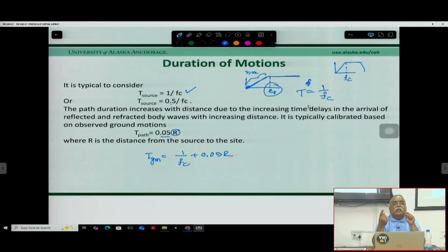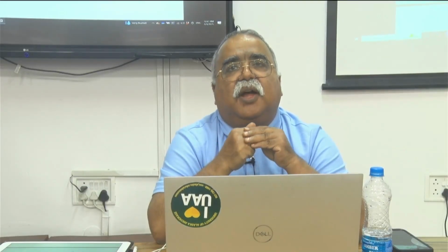One is the distance and the other is the MW. And then sit together, the computer will calculate and give you the time series. You take either the PGA or PGV, since you now want to know how to calculate, so you can do the PGA, PGV, and also the response spectra. If you have seen yesterday's code, then you can calculate the response spectra, the spectral acceleration of the earthquake, and then it will be fine.